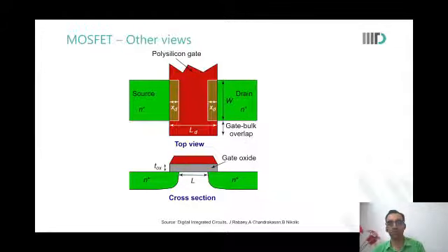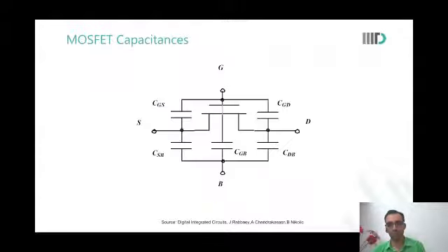So just one more thing, in the gate to drain, we are basically comprising 3 capacitances, right? So overlap, contact, and this above the diffusion layer. Yes. And same goes for the gate to source also. Yes, gate to source. Similarly, gate to body, you know, in different regions. For example, if there is an inversion layer, then the gate to body capacitance is something. But if your device is off, then the gate to body capacitance could be something else. Yes, sir. That's the most complex one, because the depletion layer would also come into the picture there.